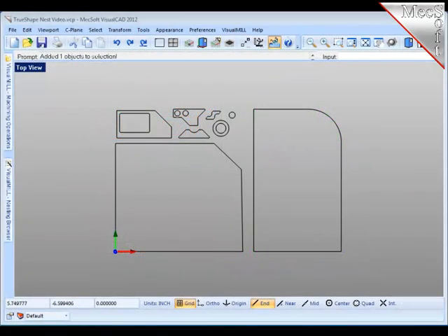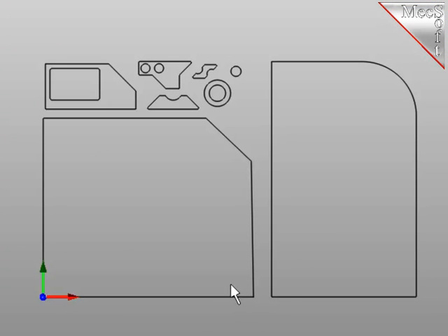First, let's take a look at what you need to do to prepare. Before going to the nesting software, you need to bring together and locate on your screen those shapes which will be involved in the nesting process. You need one or more shapes that represent the stock material or remnant. You need one or more shapes that represent the production parts that you wish to be nested within the stock material. This is sometimes referred to as staging the parts.